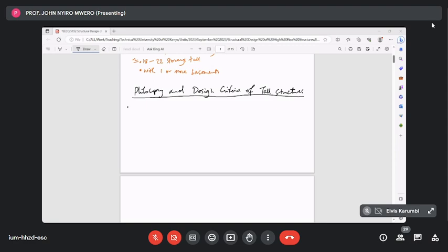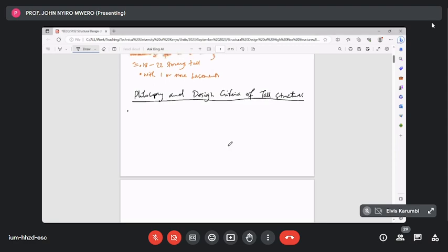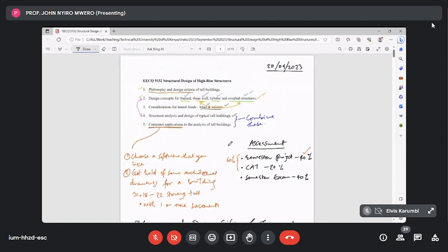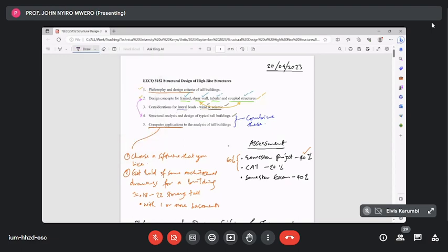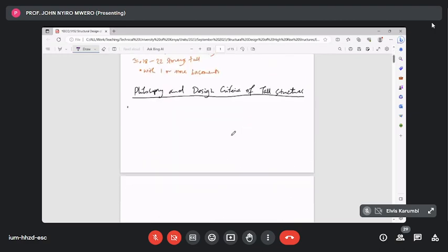Actually, I think you're right in that thought. When we start talking tall structures, it's not just about the height, but we now start getting concerned about lateral loads. The key word, what this gentleman has told us, is that now we can no longer ignore lateral loads on this structure. The structure is tall enough such that wind becomes significant and earthquake becomes significant. This basically, in a very broad way, encompasses what we would consider tall structures. Okay.